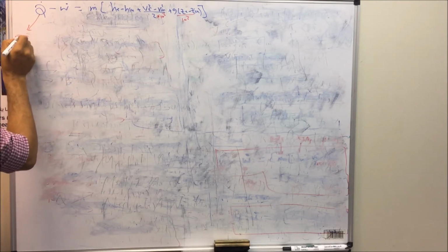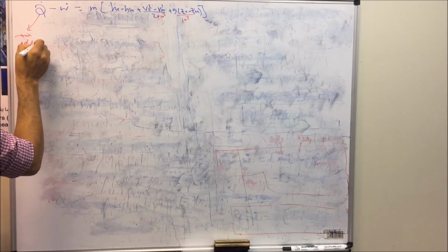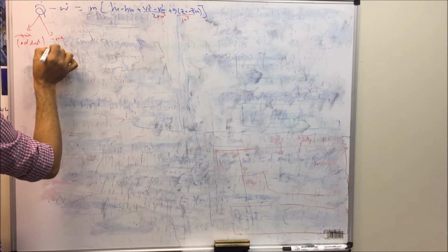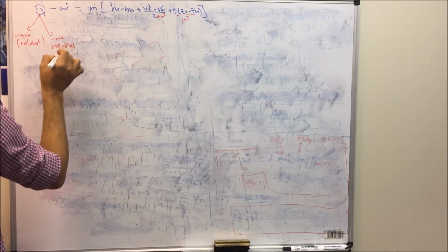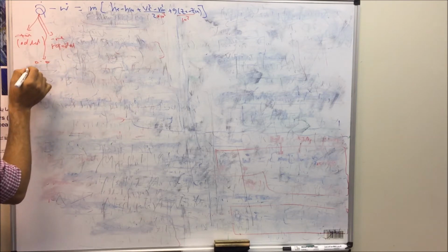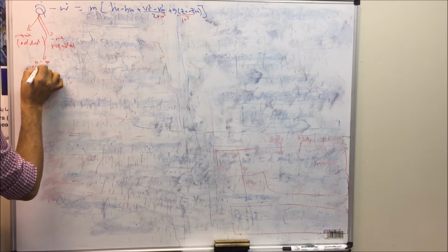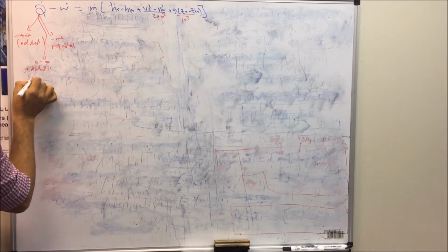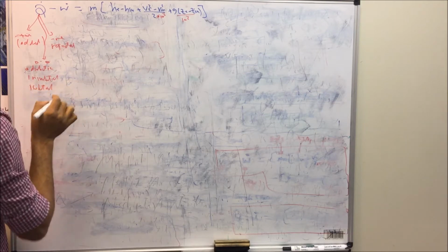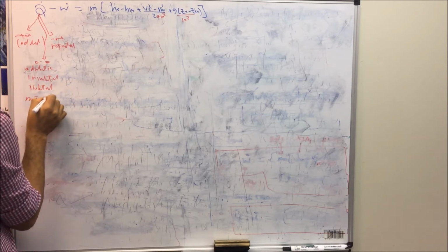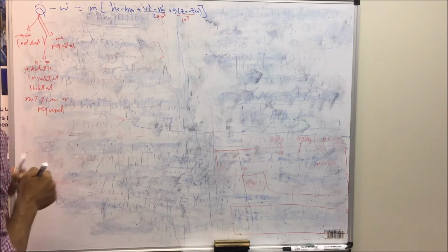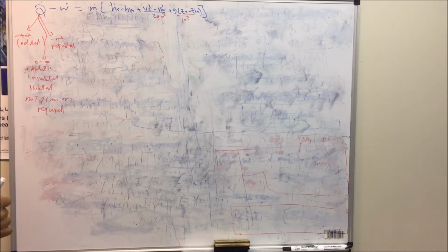It should be positive when heat is added to the system, and it should be substituted with a negative sign when it is rejected from the system. It can be 0, as I said before, when you have an adiabatic system, an insulated or isolated system, or if not given or required. So in this case also we can consider the heat transfer to be equal to 0.